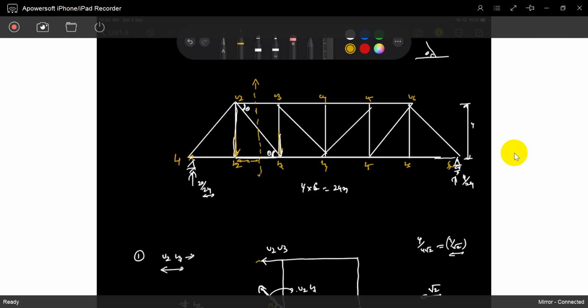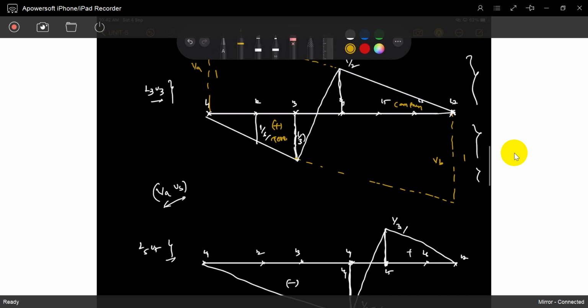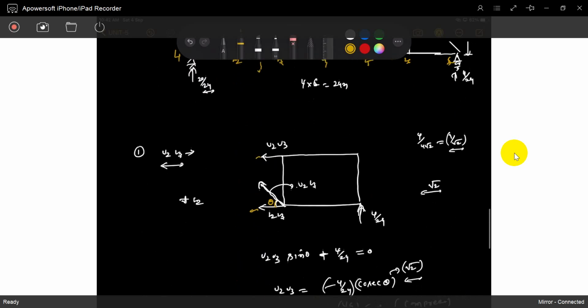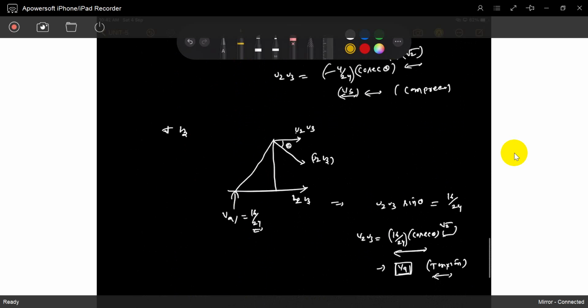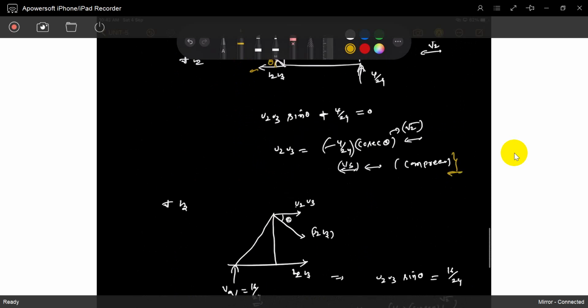Now the diagonal member is VB cosec theta. That's a small change. So understood? Up to this, previously it is a tension. Now it is a compression. Small changes will happen. No need to remember because no one asked what is the compression member.